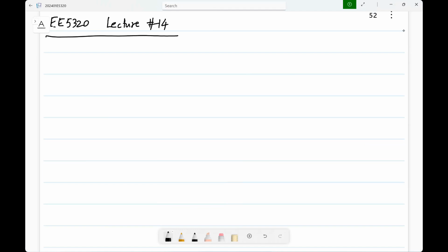And again, you either have to design them so that these variations are small, or somehow they don't matter, right? Or you calibrate them out and things like that. Exactly what you do with it depends on the particular system. But you should at least know what the effect of it is. So that we know how to do. We know how to calculate the effects of random mismatch.